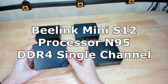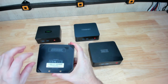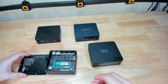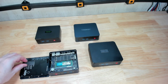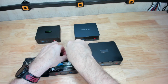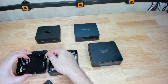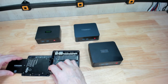Okay, so now moving on to the Beelink S12, Mini S12, S12 for 12th generation, I'm assuming. Again, it's got the 4 screws, and it has this nice little pull tab here. Just pull up on that, and then again, be careful because of the SSD. Now for the SSD, they do recommend, obviously this is covering it here, I'll go ahead and move this over to here. But it does recommend that you remove these screws here, but it's just as easy to just slide it in this way. To get it out, you might have to just push something against there to get the SSD out, or else you just remove those 2 screws. So this just slides in just like that.